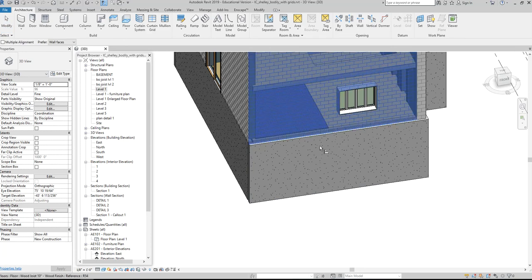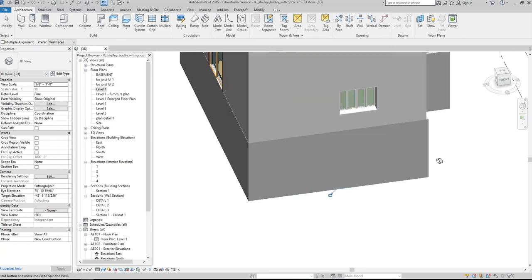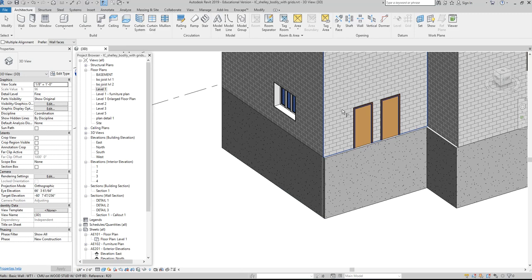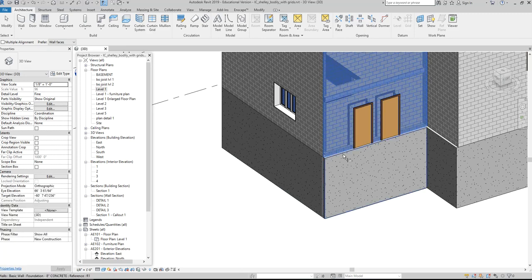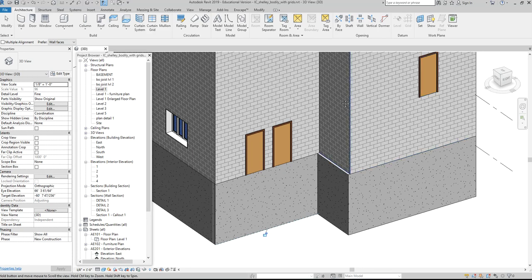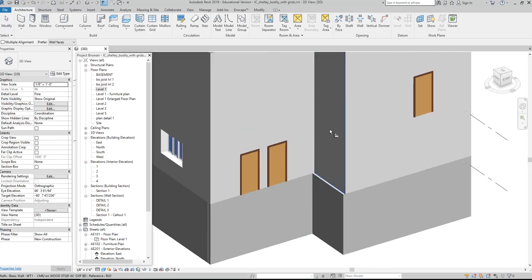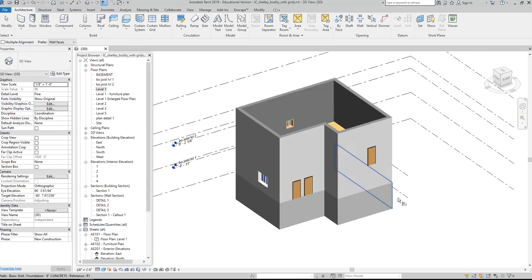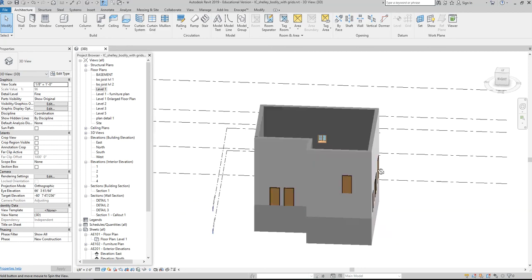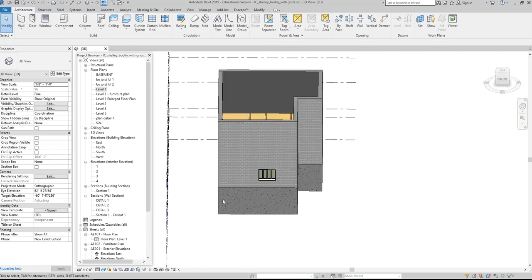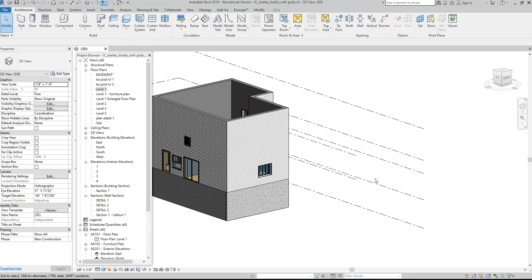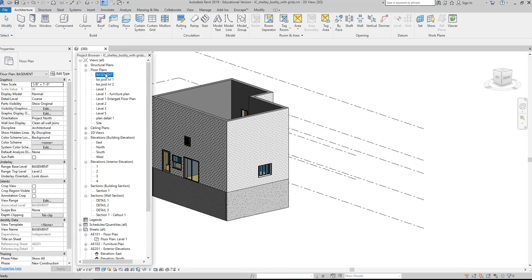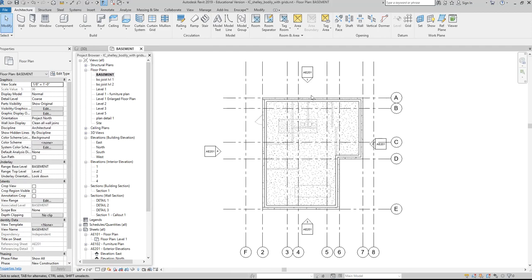AL, click, click, AL, click. And for whatever funny reason, I'm able to select this wall up here from the middle, right? AL, I can go in the middle and click, but for this foundation wall down here, it doesn't like it. So click again, and then I've got my nice foundation wall, all beautiful, looking wonderful, around supporting my building as it should, right? So now when I go to my basement level, I have a foundation wall.